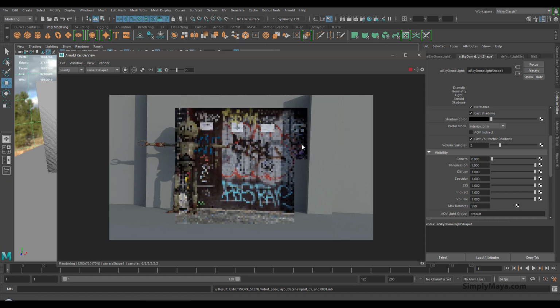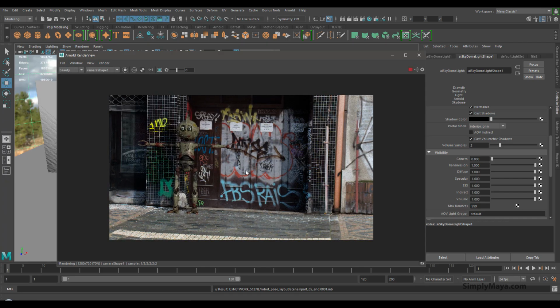So render we go. Now this might pose a problem. Occasionally this will pose a problem, simply because Arnold sometimes needs to be shut down and restarted. So if you've done this and it's causing you large issues, you might want to shut down Arnold and restart the render view. It's been a problem that's persisted now for a number of versions. It's not terribly difficult to deal with, but it can be a bit of a pain. So I'm seeing our shadows falling on our backing plate here. I'm not getting that cut off now, and our 3D and 2D scenes are fairly well integrated together at this point.